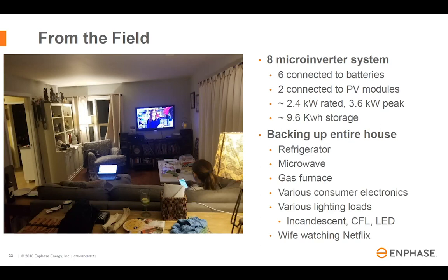Well, you still have low-speed voltage and frequency regulation to meet Rule 21 and 1547, because we're talking about control in the tens of milliseconds, right? In the tens of milliseconds, we're running basically a VAR injection technique based on deviation in frequency. So it's dynamic, at very high speed, and is able to operate fast enough that even with those other lower-speed droop controls, it's still able to destabilize the system.